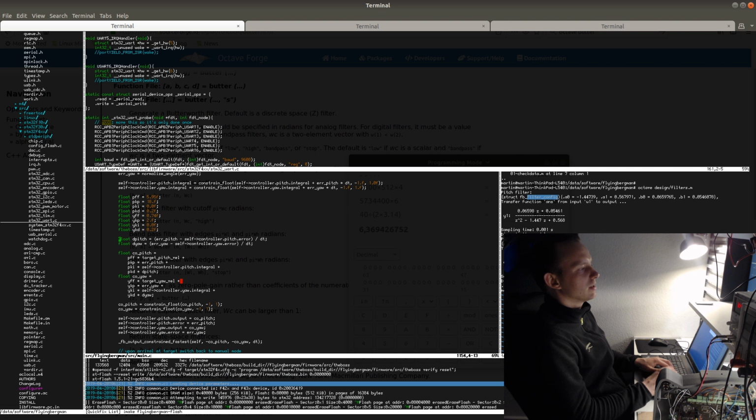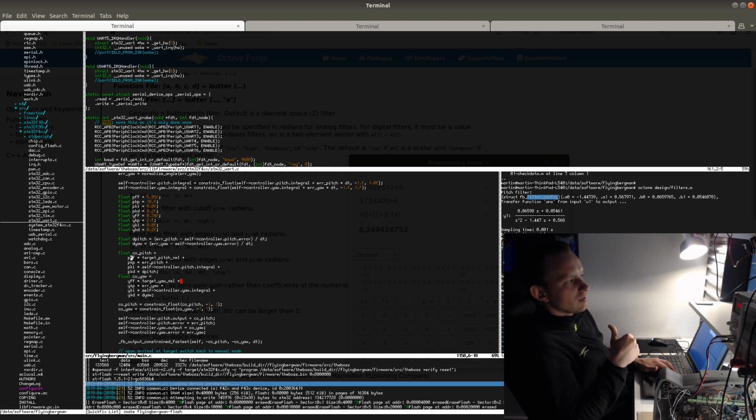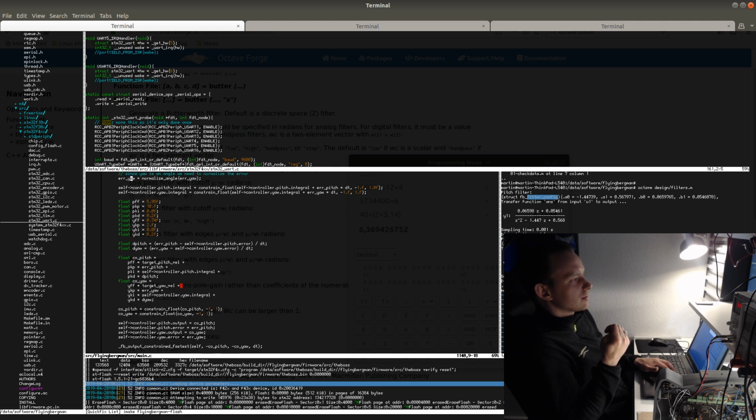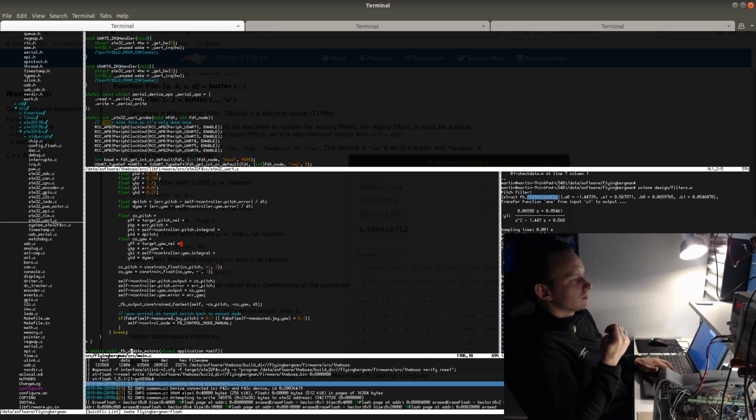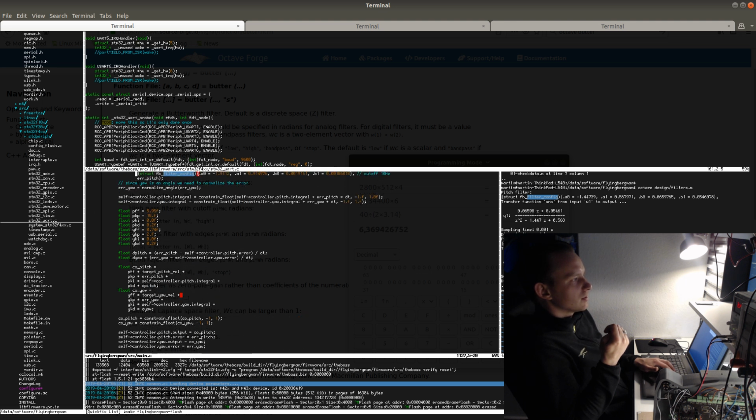The way I design the PID controller is by implementing the PID plus feed forward, and the feed forward values can be easily read out by simply exciting the system and measuring the outputs, and then looking at the DC gain of the resulting system. I can show how to do that as well. And the controller output limit set to between -1 and 1.